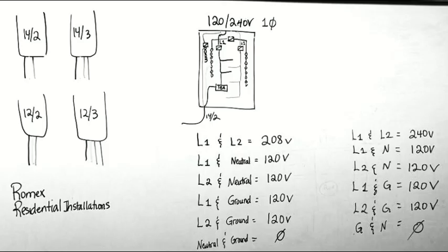Now, all of our circuits, if we wire them in series or in parallel, are always going to be running together. If we're using Romex, for example, here we have 2 wires that will complete a circuit. We have our current carrying conductor, and we have what we call a neutral. And this wire right here is only for safety. This is to be able to ground every metal part in the circuit. So this wire, which is called a 14-2, has the wires that we need to complete a circuit.